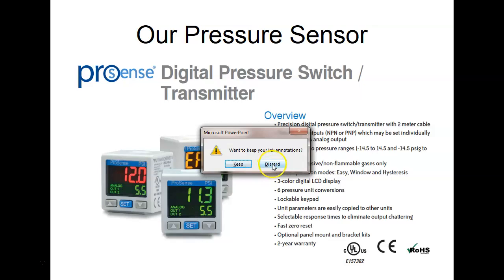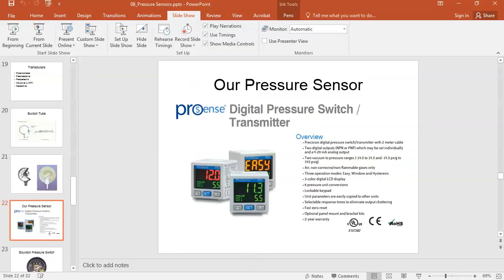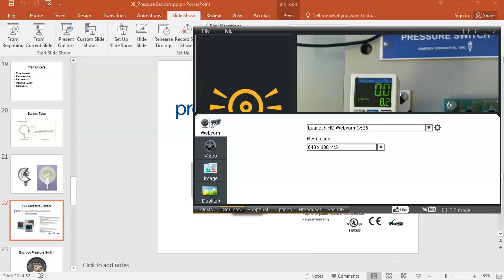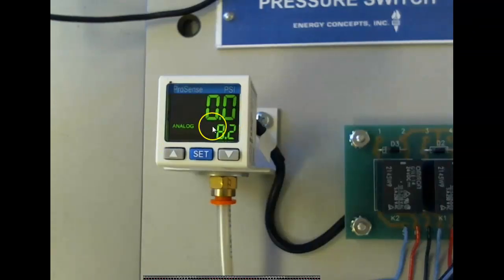And this is electronic. We'll look and see basically how this thing measures pressure. This one's showing 0 right now. So what does that mean? That means this is gauge pressure, right? Just about any pressure gauge that sits at 0 is gauge pressure. What it's done is subtract out the 14.7 psi that's acting on it right now.